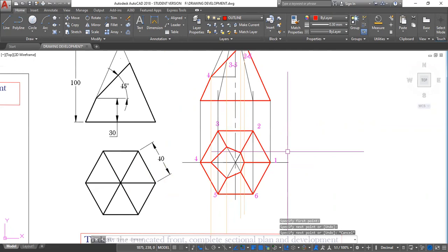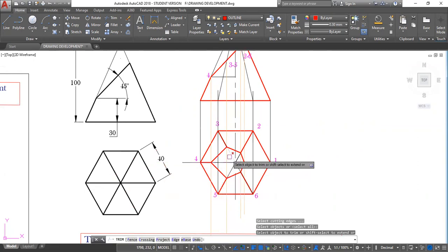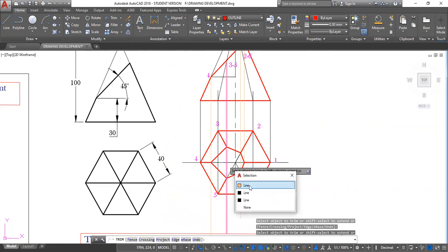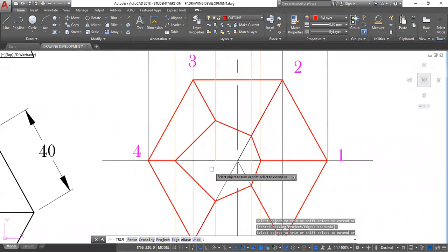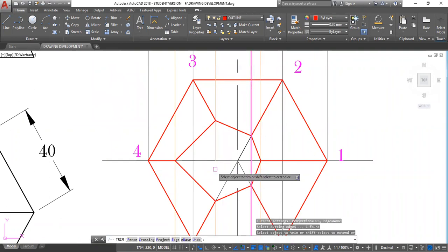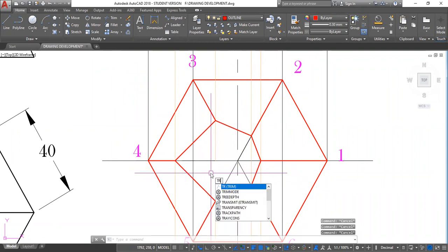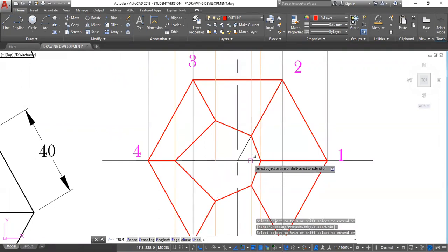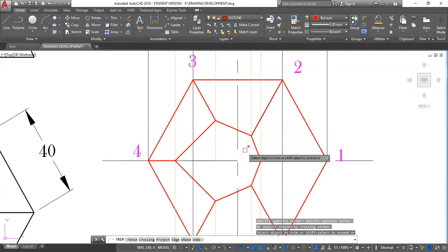Right? Now we normally hatch inside here. So I'm going to trim out inside the middle here. T, R, enter, enter. Clear this out. Polyline, trim. All right. So trim TR, enter, enter. TR, enter, enter. TR, enter, enter. These multiple lines are creating problems. Enter, enter. All right. Let those stay for now.